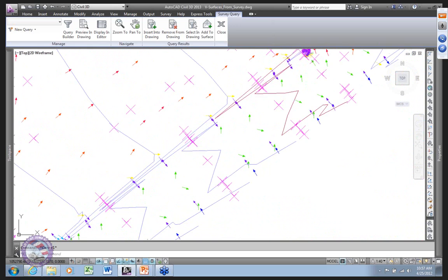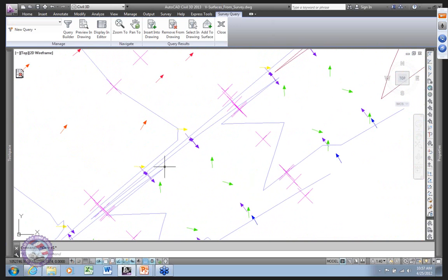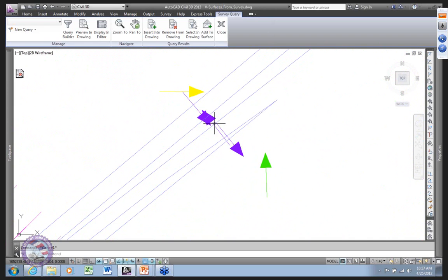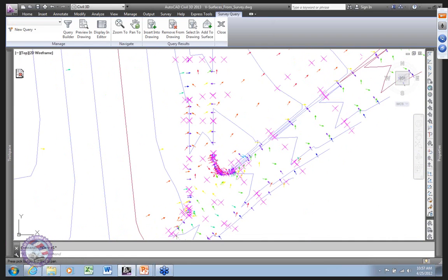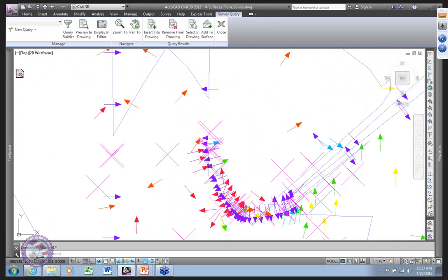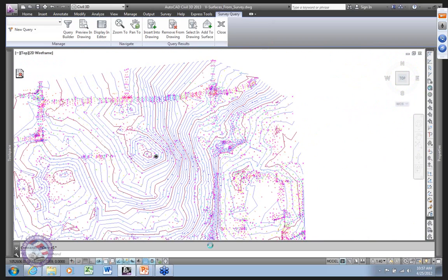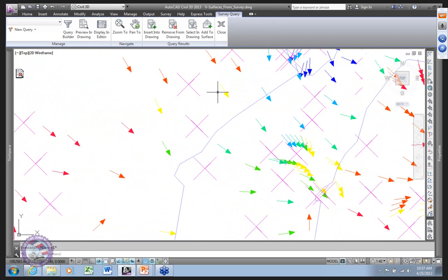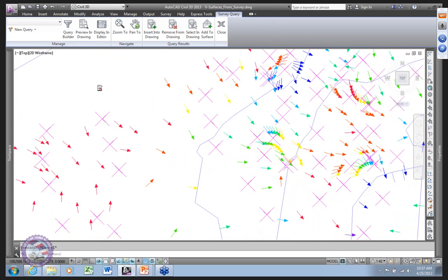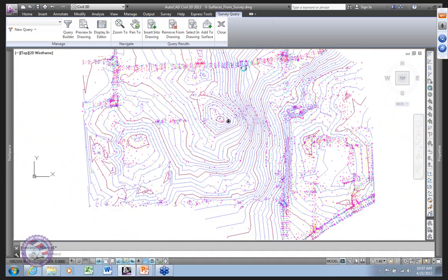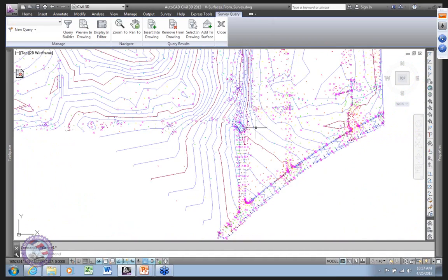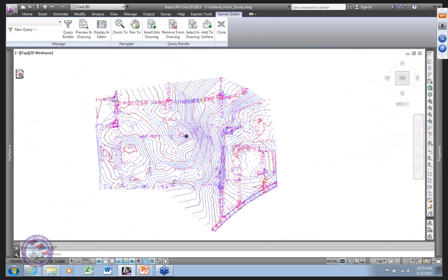Okay, down at our street, we get a bunch of stuff. Since we got a couple of ditches, we are seeing down into the ditch. Okay, so this one style can tell you right away, oh, okay, we got partial break lines, I got things that aren't making break lines. Ooh, I got a curb and gutter looking like thing here, which is radically different, for example, than up here where obviously I have no curb and gutters, I just have back of curb shots, and I've created all the other stuff that really I need to create to make a validated surface.